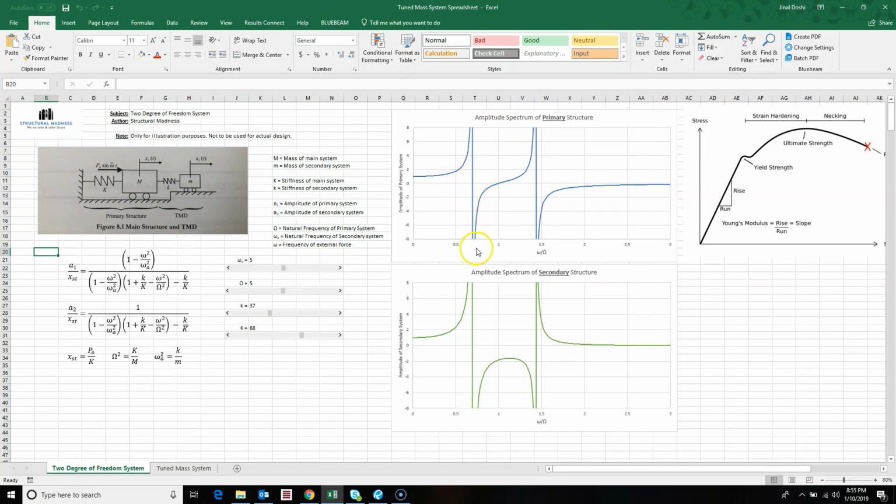You know what we can do? There is an ingenious way. You can just straight away lock the damper, and now the frequency of this system won't be over here, it will be somewhere at this point, and that will let us move away from the frequency of the exciting function. So that's how tune mass damper can help us, and with today's computation we can either switch it on or switch it off on the basis of the accelerations that the primary structure is experiencing.